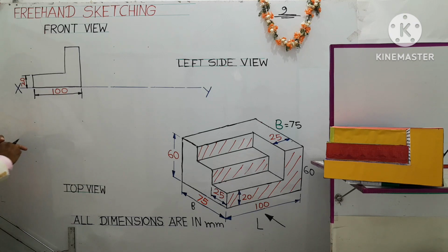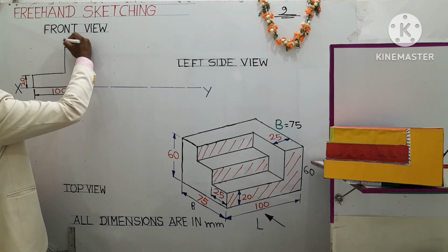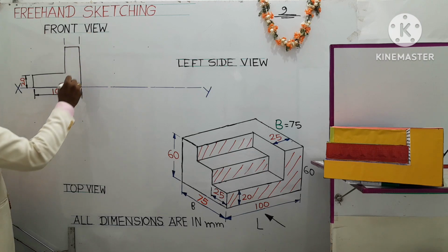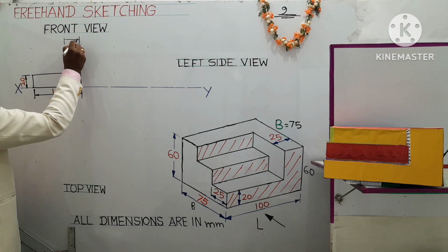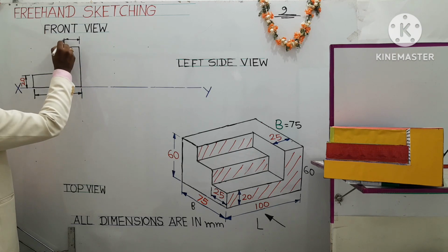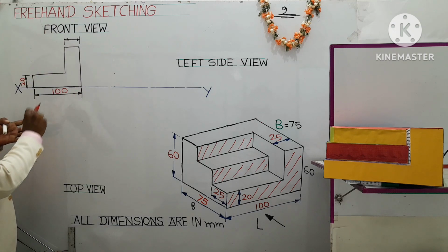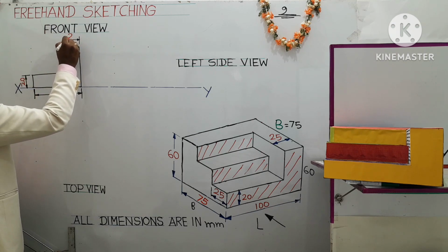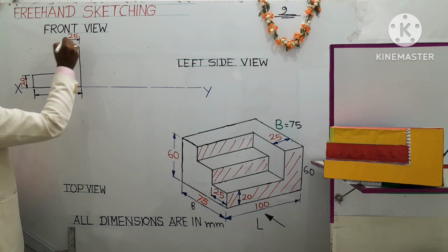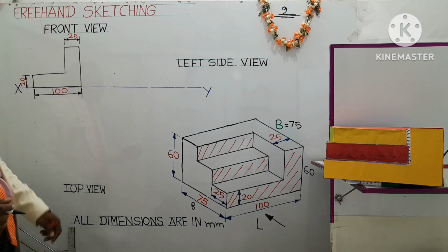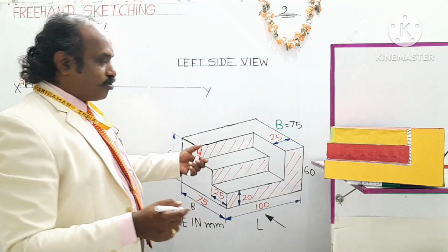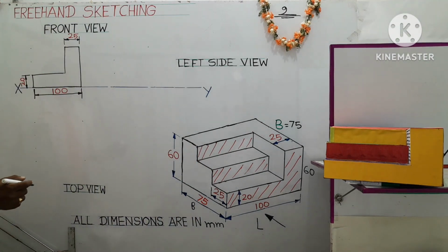Okay, and this edge on the top surface having the L shape, that is the yellow colored part. Here this distance is given, refer to the diagram, as 25 mm. I used a different color, but while drawing on the drawing sheet, you can carry out the writing work in an HB pencil so it appears dark, so that one who reads the diagram or the drawing is able to see the numbers visibly. Okay.